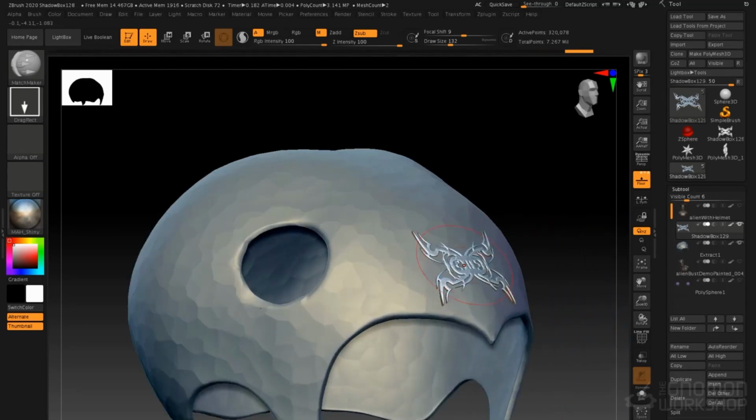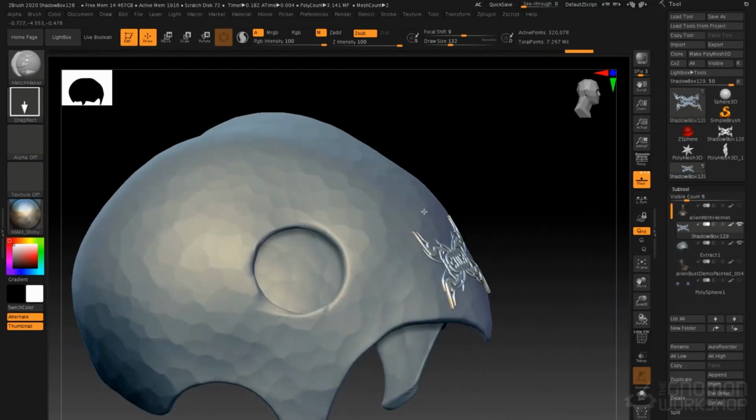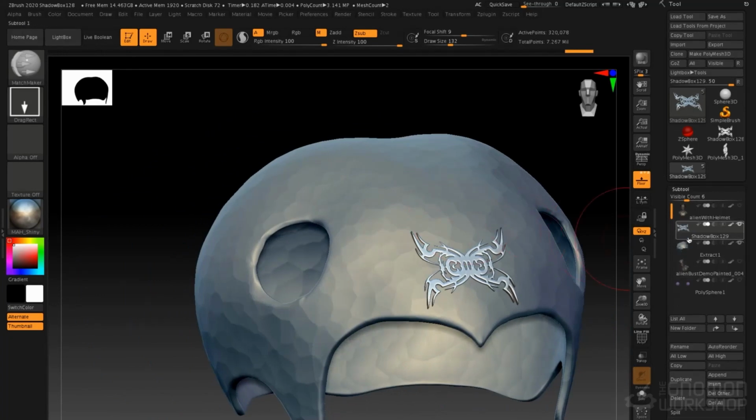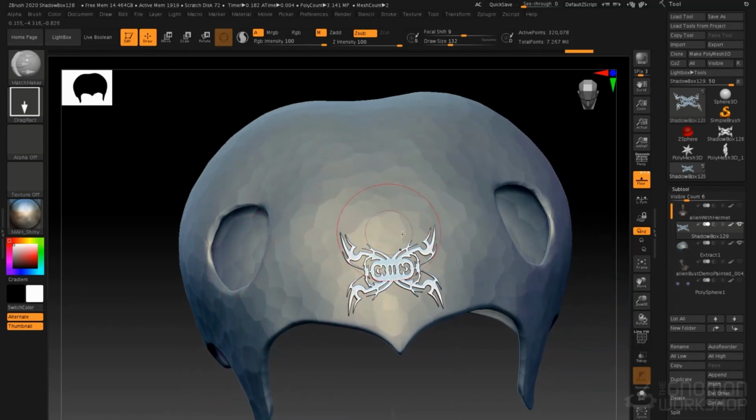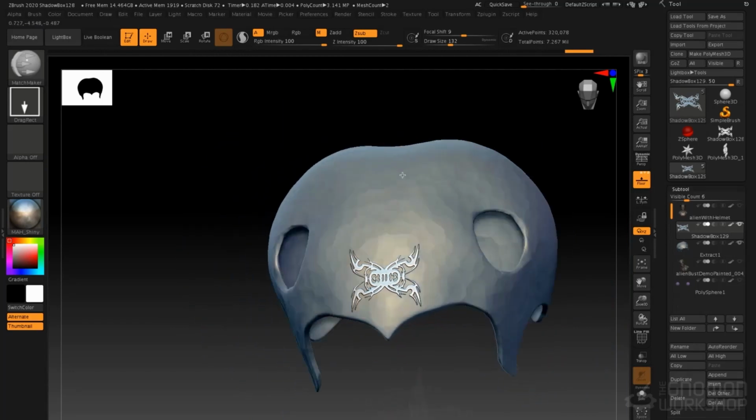Now, any object can be matchmade into the object beneath it. All you do is place it, orient it so it's looking down the projection angle, and then use your Matchmaker brush to click and drag, letting go off the surface. That should conform it to whatever shape is underneath it.